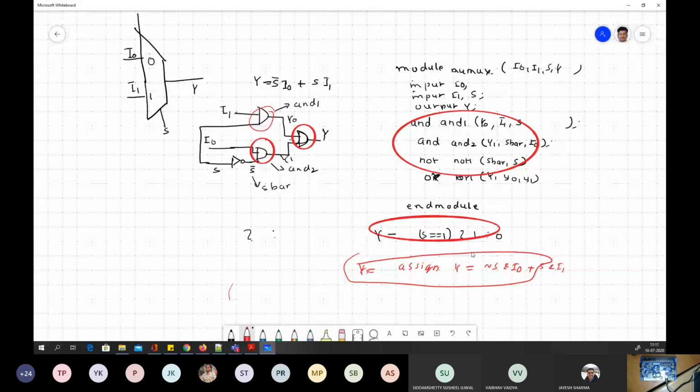For instance, if you describe it at this level, maybe your standard cell library already has a multiplexer. It just takes a multiplexer, it doesn't even implement it. But if you implement it using the structural style, where you want exactly this one, then though the standard cell library might have a multiplexer, it might go and implement it using only AND gates and all those things. That might not be efficient.